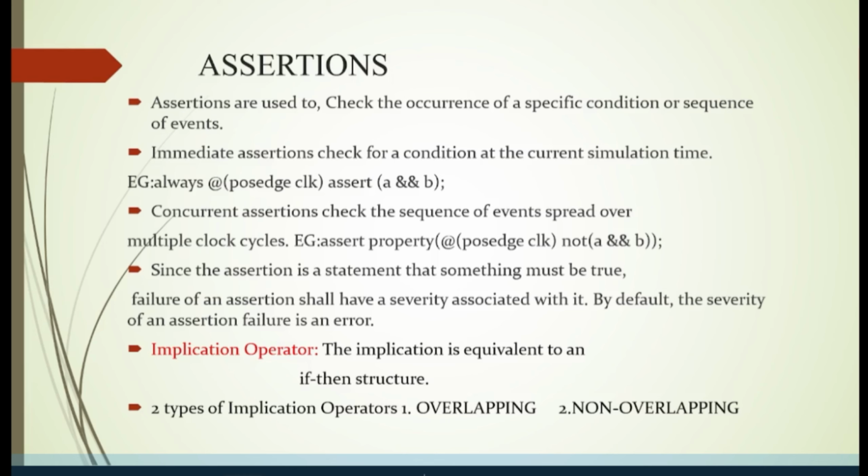Then comes another key feature in SystemVerilog, which is assertions. Basically, assertions means we are checking something. For example, when you are verifying the design, you need to know how the design is behaving. You are verifying whether the design is behaving in the way you want. When you pass some stimulus to that design, it needs to behave correctly. For example, when you are designing an adder and you pass the stimulus 2 and 2, it should give you the output as 4.